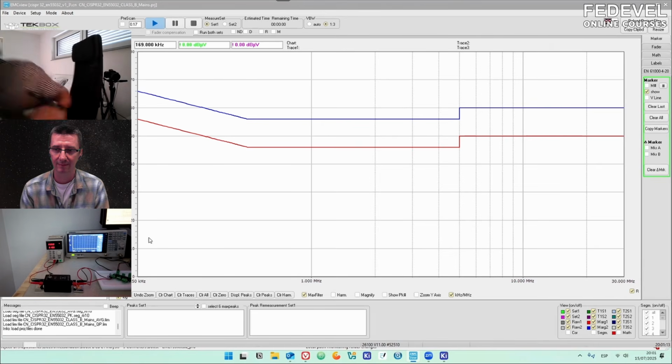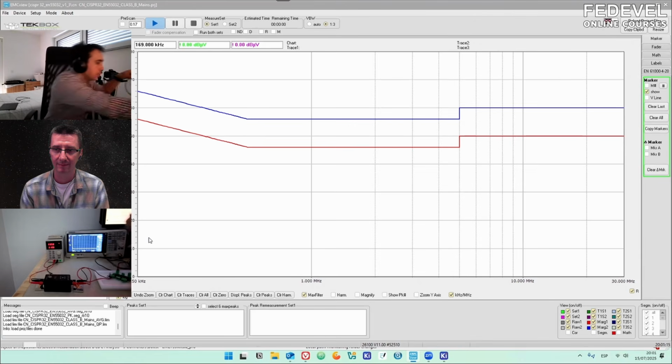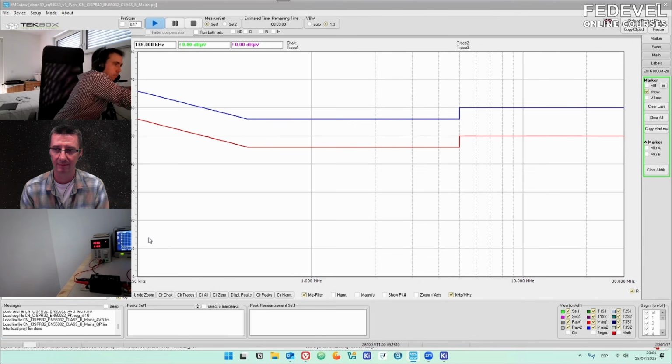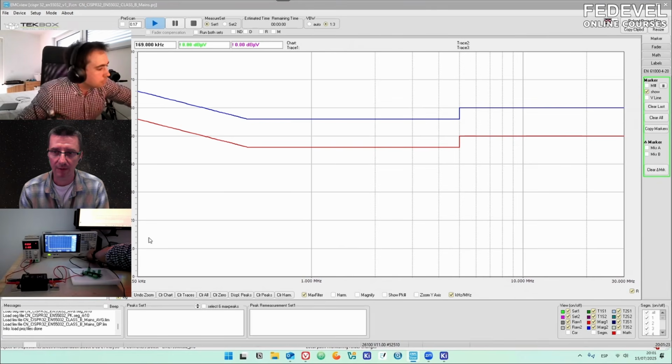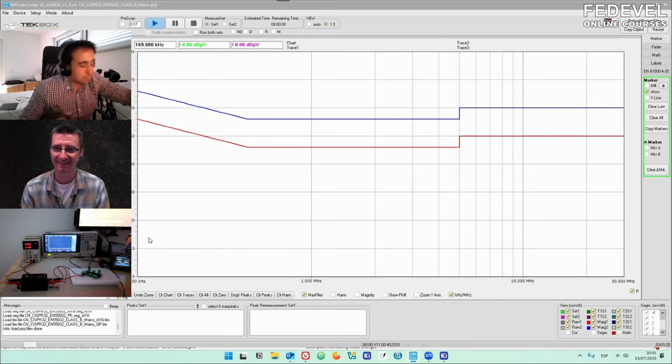And what I like about this test is that it's very easy to replicate at home. But for this test, I think you need to have some kind of metal plate or something? That's correct. You know already the details. Yes, so you need a ground plane. In an EMC lab, that ground plane is made of copper. So people use a copper surface. For pre-compliance measurements and for home measurements, you can use aluminum.